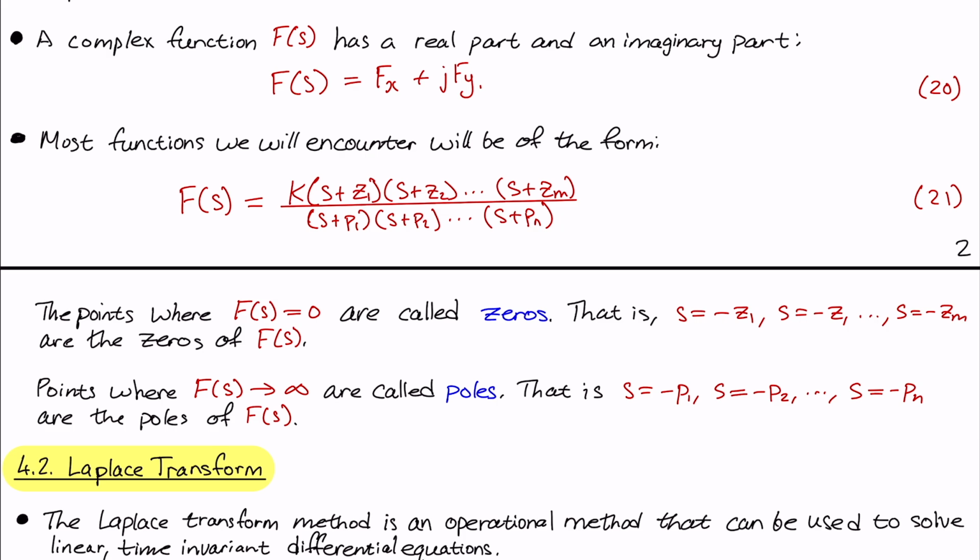So I think when we did steady state vibrations and we looked at resonance, we found that the system or the response would blow up whenever the forcing was equal to the natural frequency omega n. It's a similar kind of concept here. In this case, the natural frequencies are equivalent to poles, in this kind of context.